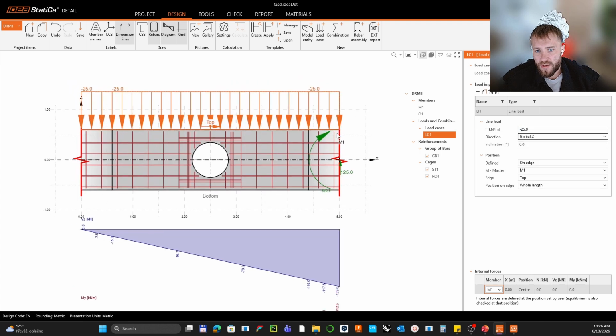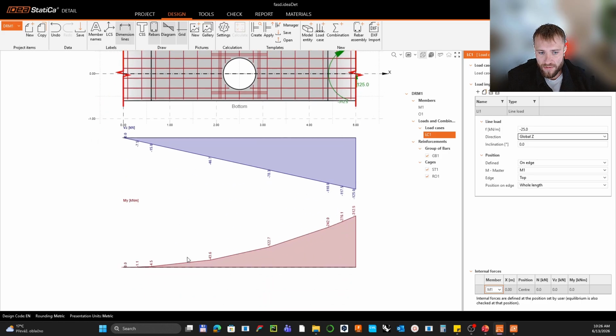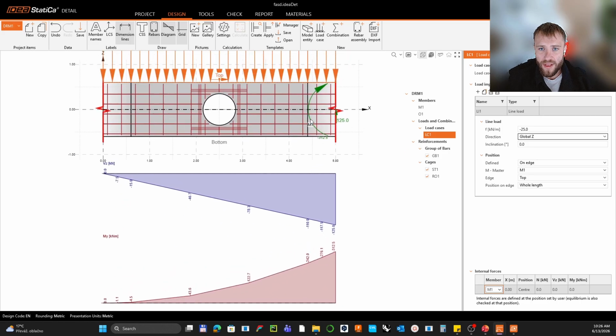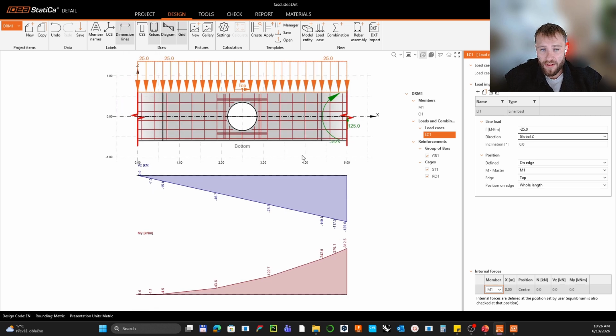As you can see, once you set up the load, of course, the model is not flying in space. It needs to be anchored somewhere, and here is the support actually at the end. This is the reason why you need a properly defined equilibrium, because it's anchored somewhere in space. And if you put the force, you're able to see it behave as a cantilever. Great.